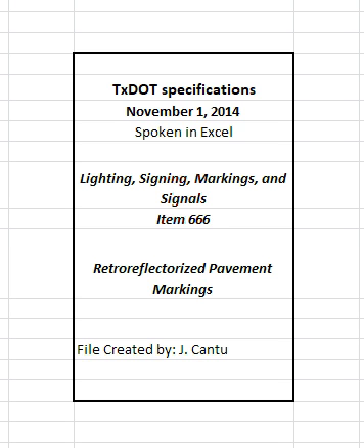4.2.3 Sealer for Type 1 markings. Apply a pavement sealer to old asphalt surfaces more than 3 years old, and to all concrete surfaces before placing Type 1 markings on locations that do not have existing markings, unless otherwise approved. The pavement sealer may be either a Type 2 marking or an acrylic or epoxy sealer as recommended by the Type 1 marking manufacturer unless otherwise shown on the plans.